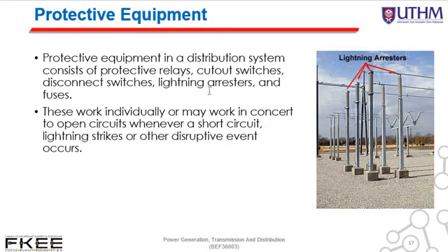So another component of a distribution substation is the protective equipment. Whenever a short circuit, lightning strikes or other disruptive event occurs, this distribution system will be safeguarded by the protective equipment such as protective relays, cut-out switches, disconnect switches, lightning arrestors, and last but not least, fuses.